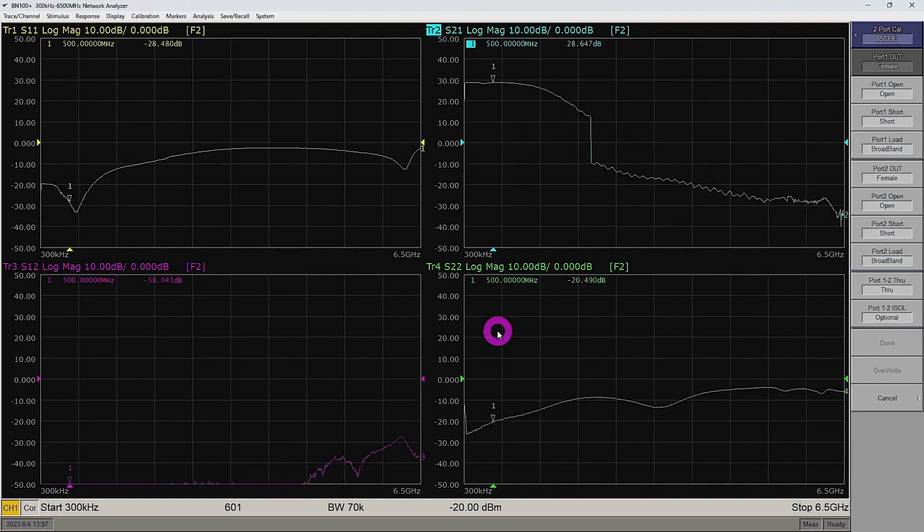Let's go all the way to 50 Hertz or so. And at 50 Hertz, we should see some cool effects. Here we go. So we see this kind of rolling effect. That's because we're aliasing the update rate of the VNA combined with the actual waveform I'm applying. Now right now we're sitting at a -20 dBm input power, which is pretty important because we want to make sure that we do not saturate this amplifier.